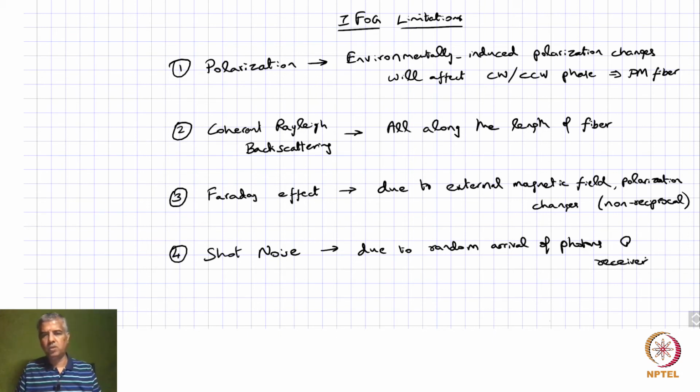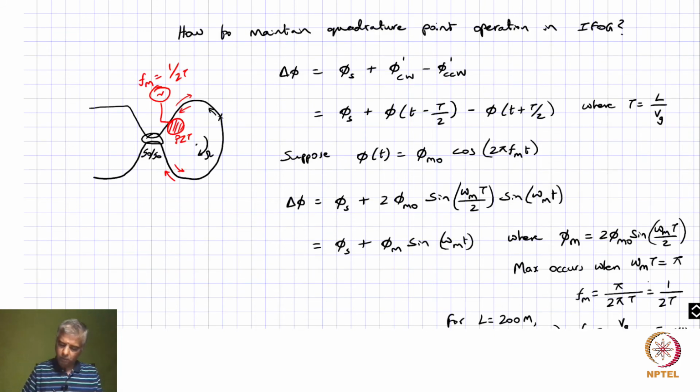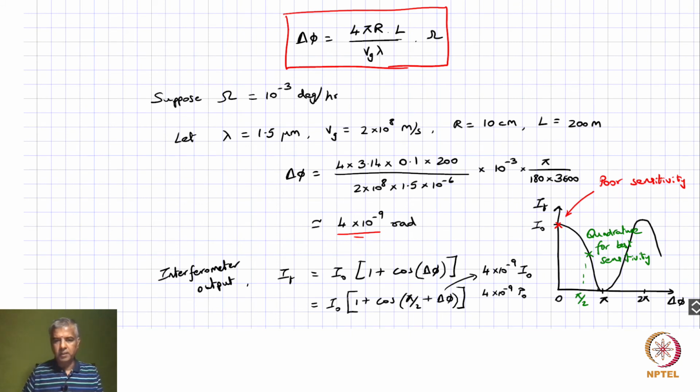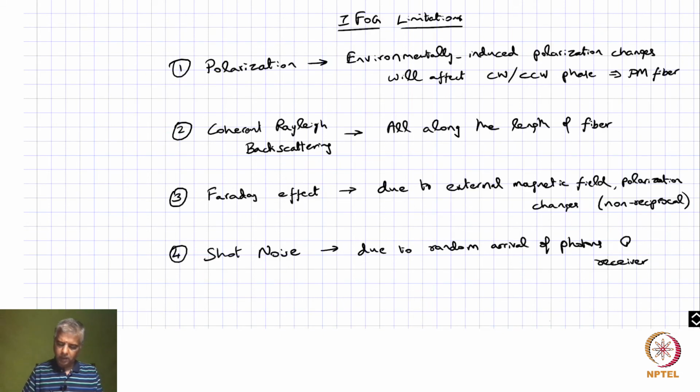So that can also introduce some fluctuations, because finally we are looking at changes in intensity, and like we saw previously, to increase your sensitivity, you need to increase I naught, the intensity for each of those waves, and if you increase I naught, then you have more light incident on the photodiode, and that actually causes shot noise. So we need to be wary about that as well.